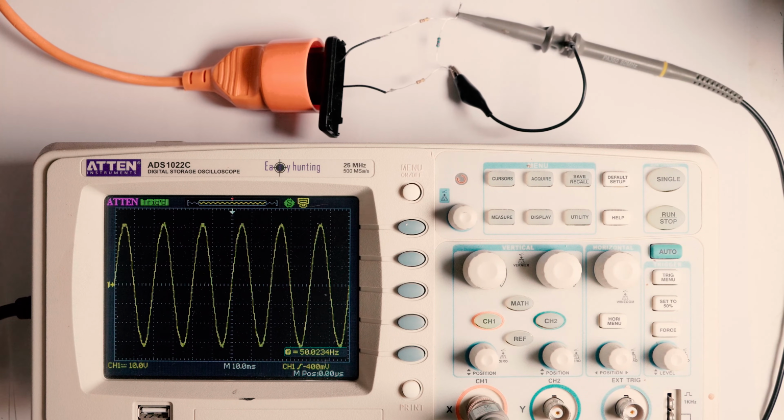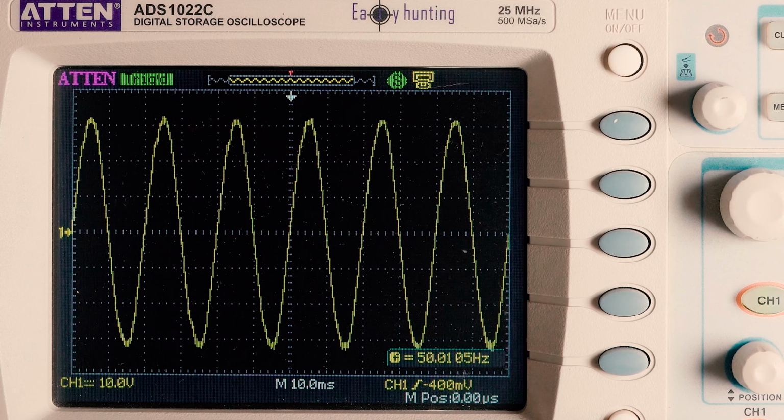So here's our sinusoid. The scale is graded with value of 1 division equal to 10 volts. And now let's count voltage from 0 to the peak. What do we see? 32. That means the real sinusoid amplitude is not 230, but 320 volts. Why? Have we been deceived all this time?